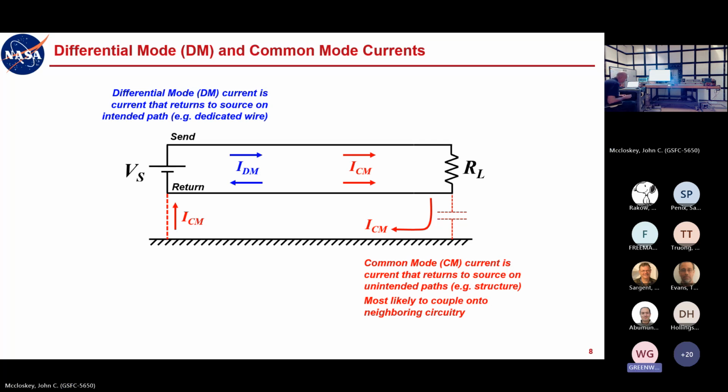Well, maybe the test setup has changed then, because I didn't see a way to say, okay, hey, there's a stray capacitance there between the ground plane and the body of the converter. Well, the converter is not tied to the chassis because it's not a metal chassis. Well, there's got to be some capacitive coupling to get you back to the converter chassis, right? So really that's getting way into the weeds here, Wayne. I'm happy to talk to you about this offline.